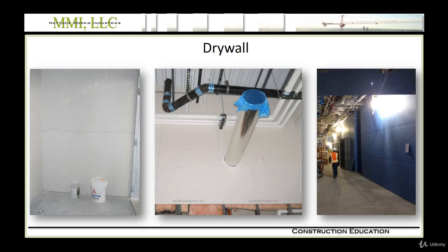So that's a combination of fire rated and mold and water resistant. And this is a completed corridor. In this case we used the mold and water resistant drywall everywhere because our enclosure wasn't quite done when we were installing partitions. And this particular wall is ready for finish. So one thing to notice is this corridor is pretty jam full of MEP systems at the top.